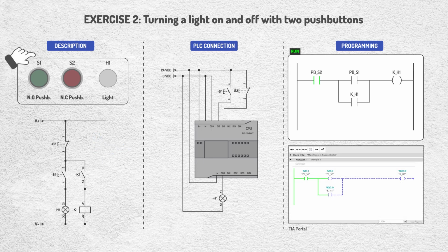The operation is simple. When the start push button is pressed, the light must turn on and remain on even after the button is released. The light will only turn off when the stop push button is pressed.